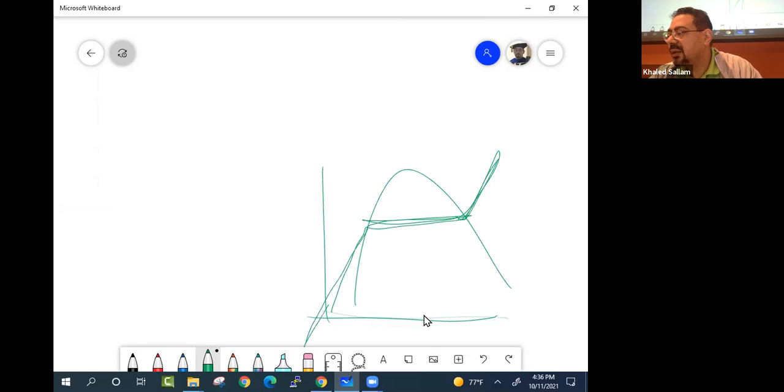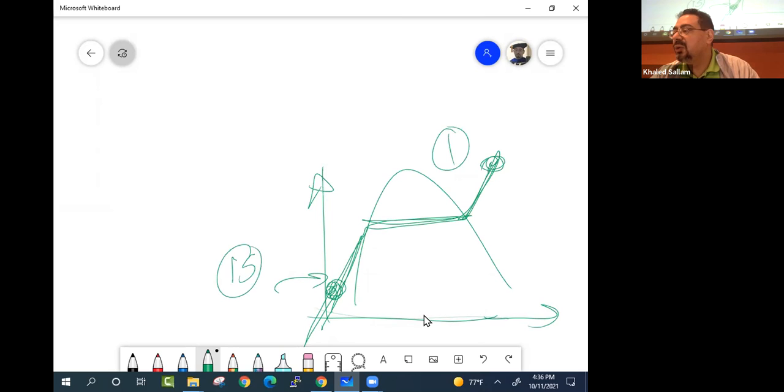What is that line that I'm plotting here? Constant pressure. And we would say the water goes into the boiler at, say, state 4 or 15, and then leaves at state 1 ready to go to the high pressure turbine. And if there was a reheat, you would take it here at that pressure, you reheat, and heat up till here, or sometimes all the way up to the original temperature. Okay, and then they expand again.